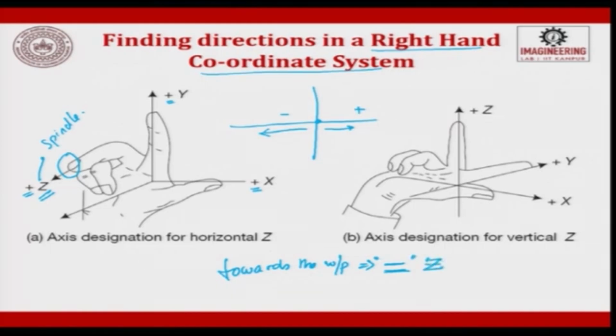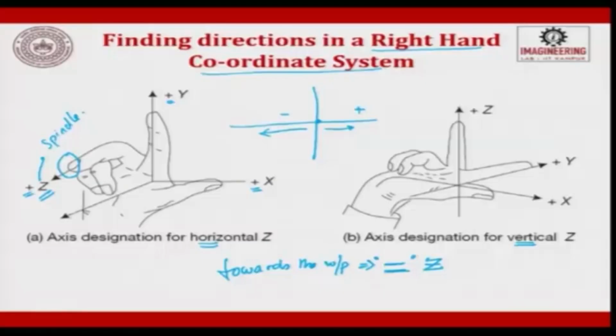It can be z axis, x axis, y axis, right. And as far as the machines are concerned, they will have 2 types. One is called horizontal, the next one is called vertical. So, looking at the orientation of the spindle axis, you put your perpendicular finger to the plane as the z axis. The other 2 axes are fixed. By this way they fix the axis and give the plus and minus sign to the coordinates.